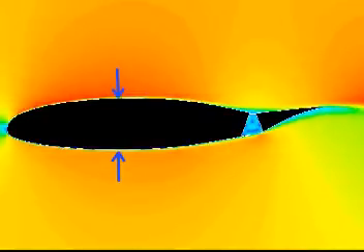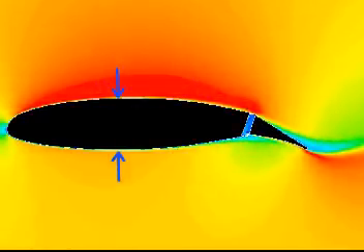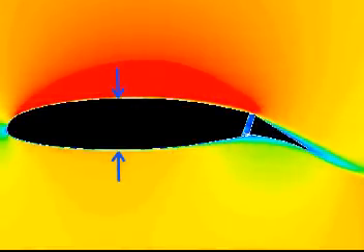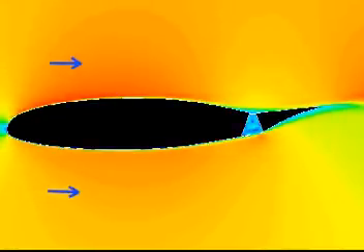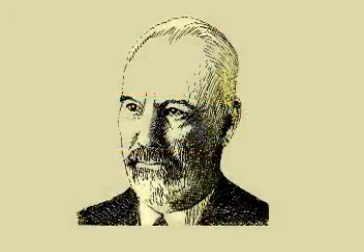Very close to the wing's surface is a thin layer known as the boundary layer. In it, viscous forces are important and cannot be ignored. However, outside the boundary layer, viscous forces are negligible compared to the inertia of the flow. We call this the outer, inviscid flow region. This distinction, due to Ludwig Prandtl, was one of the key developments in 20th century fluid mechanics.